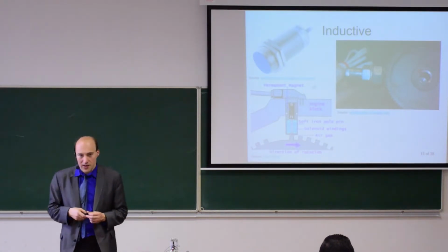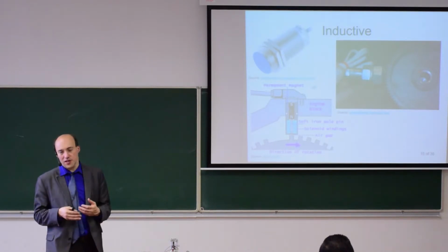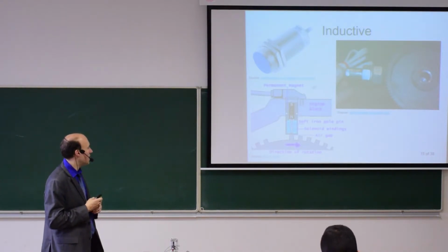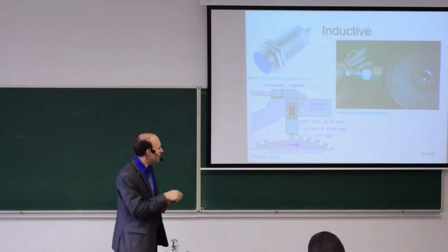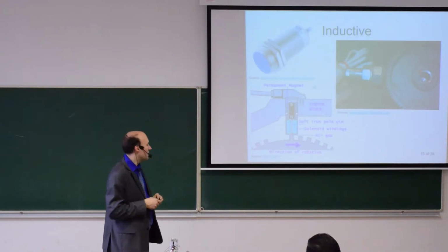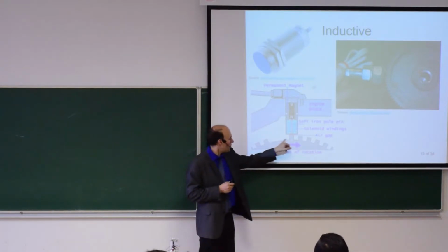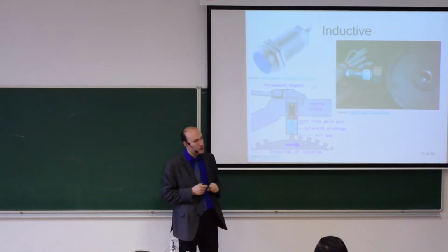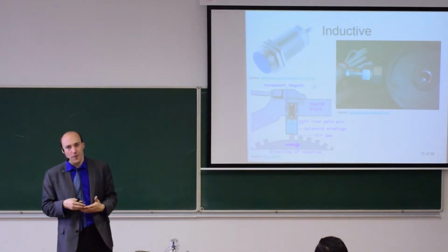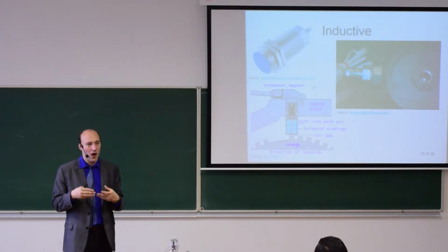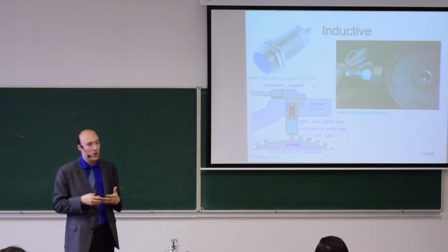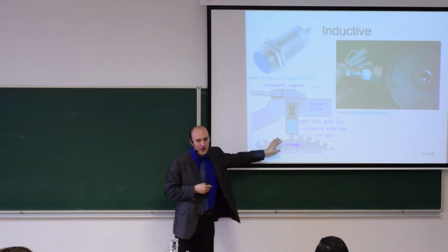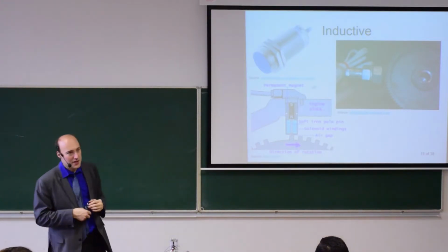From the outside, it looks quite similar to an inductive proximity sensor. You can also use inductive proximity sensors in most applications, but you need to be very careful about the air gap size, the air gap distance. Here you can see also that you can remove some teeth, and this allows you to get some reference position. So if you need to time some valves, for example, or some engine control, you can do it easily with this kind of sensor and with this free space where you don't have any teeth.